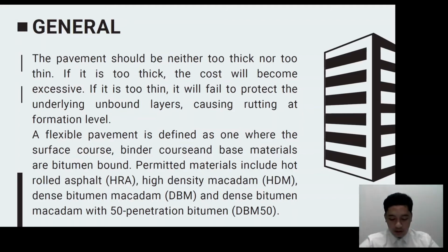The pavement should be neither too thick nor too thin. If it is too thick, the cost will become excessive. And if it is too thin, it will fail to protect the underlying unbound layers, causing rutting at the formation level.